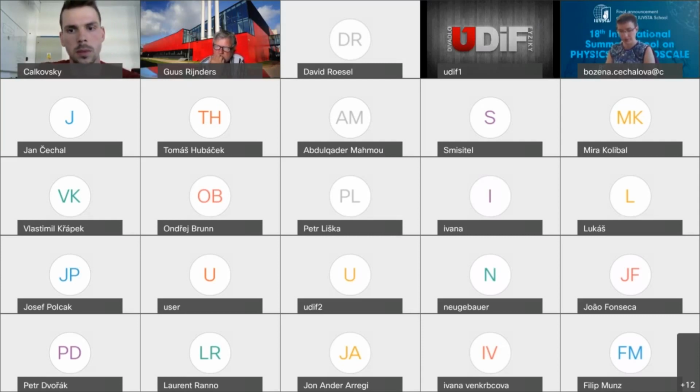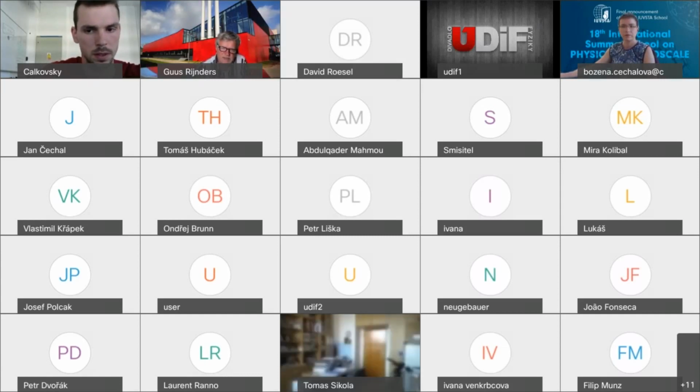Yeah. Perfect. Maybe let's make it the last one. How do you control uniformity and stoichiometry of films prepared on large size substrates? We know that the plasma volume has a very limited size, right? So isn't that a problem? That's indeed a problem. What we typically do is control the laser parameters quite well. And actually for PZT, it's not a big issue because it's already a solid solution between lead zirconate and lead titanate.